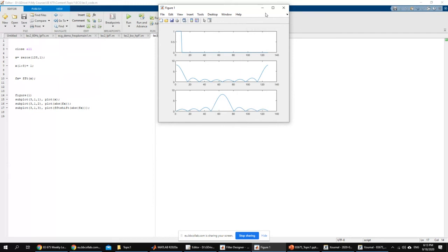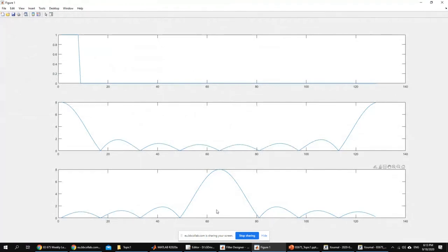So now I know how to compute the frequency domain. If I wanted, for example, to remove a particular frequency, all I have to do is go and make the frequency I don't like zero. Very simple. So for example, if I decided to remove the DC value, I can go to point 65 and make it zero. That's it. If I wanted to have a range equal to zero, that's fine. I can do that as well.